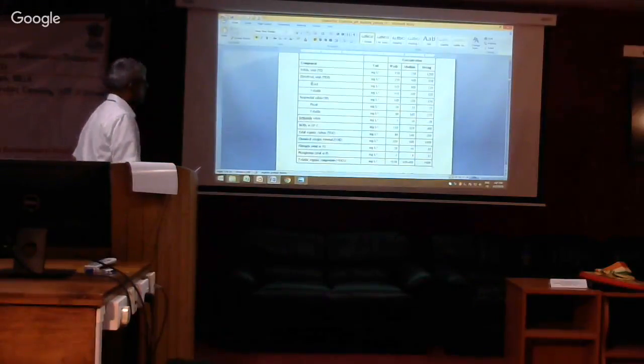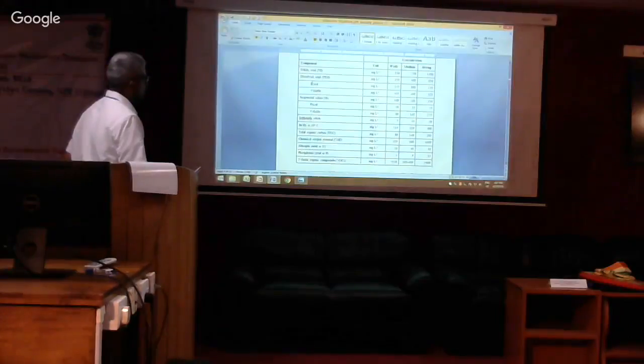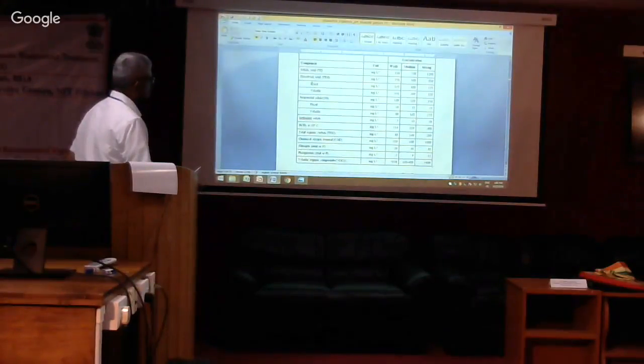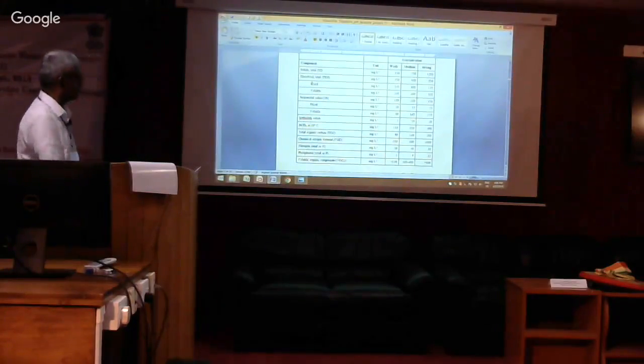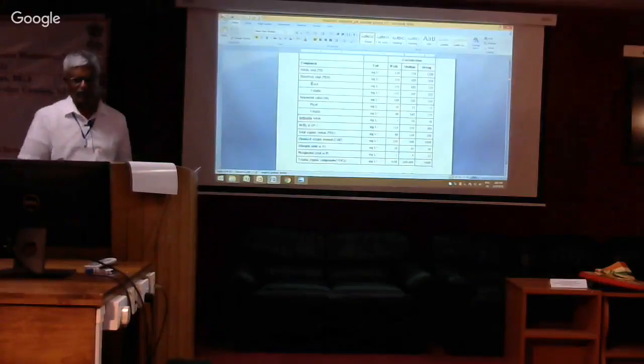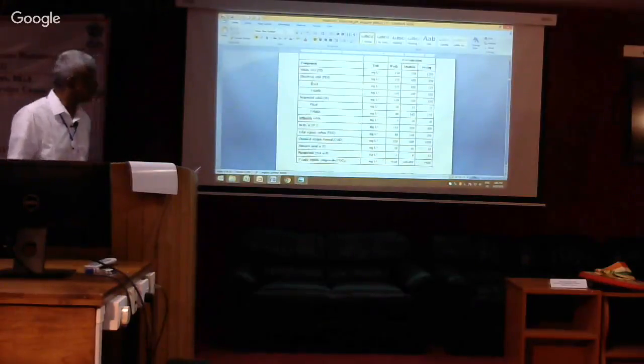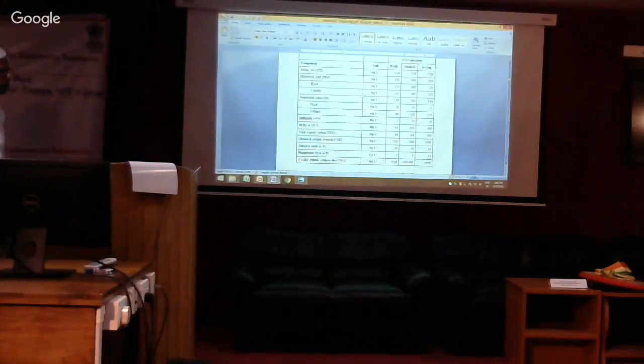But for our purposes, perhaps the most useful information is that if you're looking at a municipal wastewater, the chemical oxygen demand is somewhere between 250 and 1,000. And the BOD is somewhere between 100 and 200. And when we say BOD, of course, it's always BOD 5, as you know. Okay? So this is typical municipal wastewater.